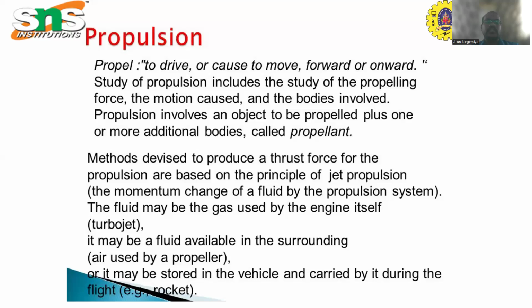This system accelerates a gas working fluid in one direction, and the reaction to this acceleration creates a force in the opposite direction, propelling the vehicle forward. The amount of thrust generated depends on the mass flow and the exit velocity of the gas. These are the working principles of propulsion.